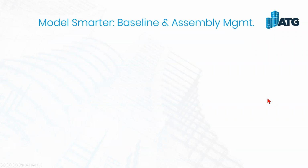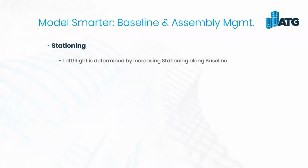Now, that's as far as our object names are concerned, but we're also going to want to have a plan and some standards for how these baselines are going to get put together and how our assemblies are going to get put together. So as far as our stationing is concerned, I covered this pretty heavily in the previous webinar, the one on connected alignments. Whatever is on the left side of our corridor or the right side of our corridor is determined as we follow our baseline by going forward in stationing.